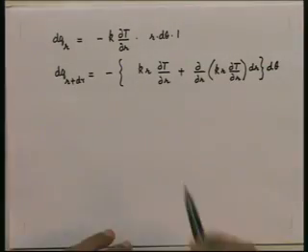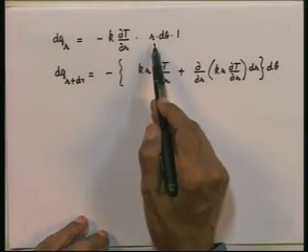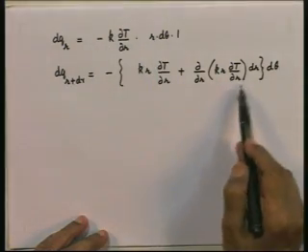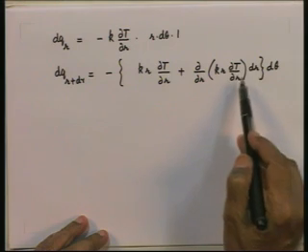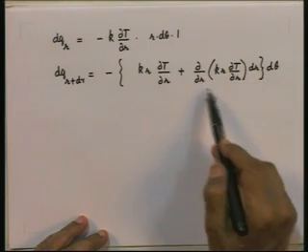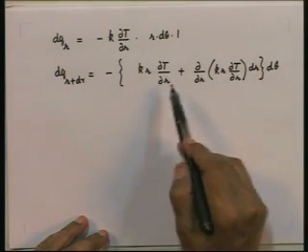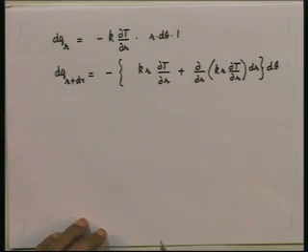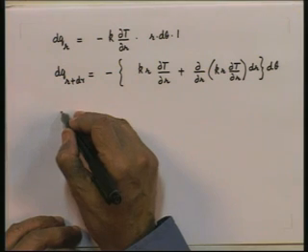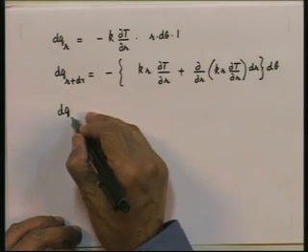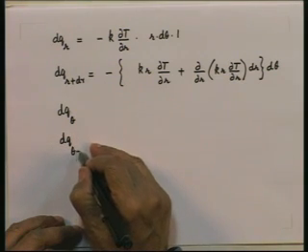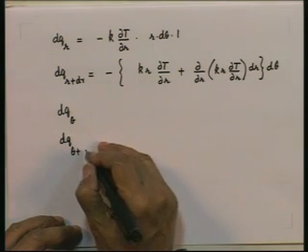All right. The quantities varying in the r direction are k, dt dr and obviously r. So, all this k dt dr into r has to be taken inside the differential. d dr of all this multiplied by dr is the amount of variation that occurs when we move from r to r plus dr. Similarly, we can write down expressions for dq theta and dq theta plus d theta.